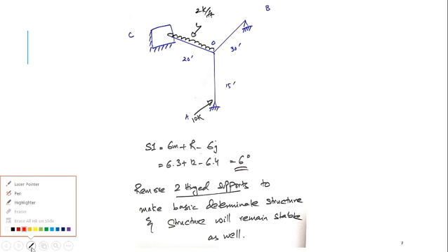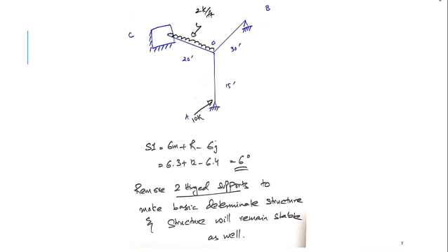The flexibility matrix is actually independent of loading, so I have just changed the loading. In the previous lecture you could see that the load was applied here, and the distance was 7.5 feet and 7.5 feet. The load was the same, that is 10 kip, but I thought while solving the question it would be a bit difficult for you because sectioning would be changed. So it's better to apply the load at the corner or at the support. So I have just changed the load, so the flexibility matrix would remain the same.